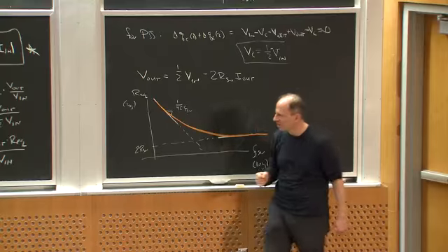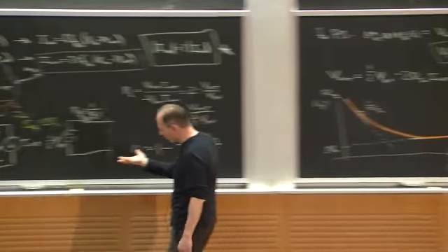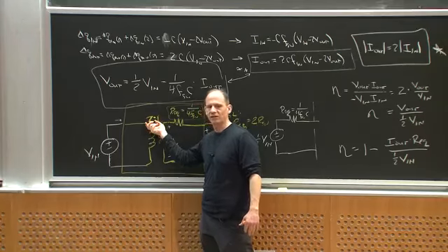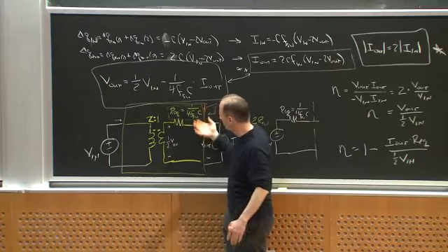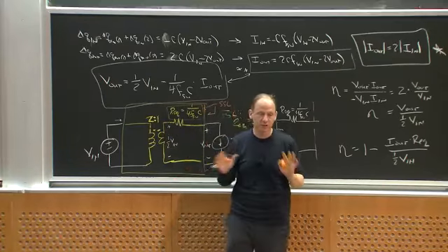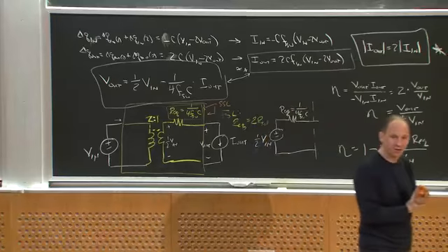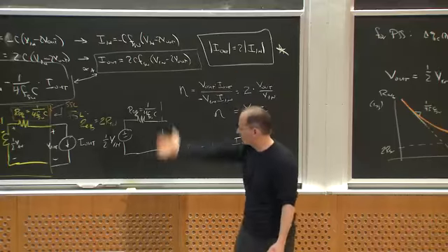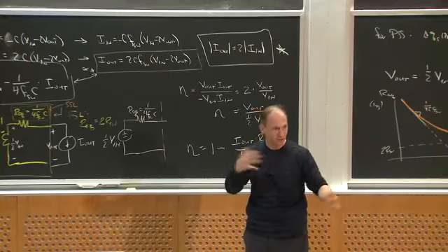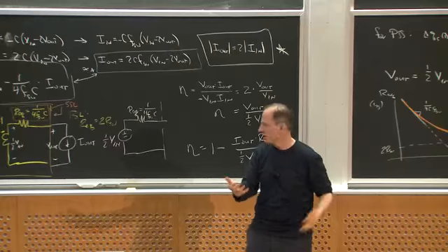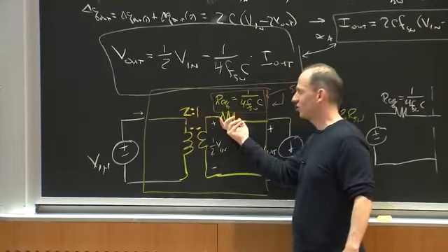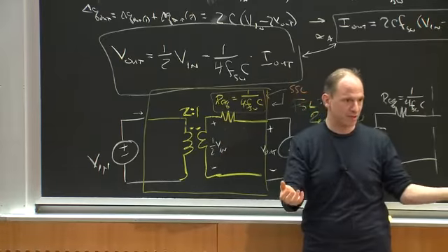And the result of this is if what I want is a fixed conversion ratio close to this, I can get extraordinarily high efficiencies and power densities. If I deviate the voltage conversion ratio away from that, then the efficiencies start to droop. But for what they're good at, switch capacitor converters are very hard to beat. And if I was to analyze any other switch capacitor converter, it's the same deal. It's some charge transfer analysis through the different capacitors, and I use charge balance, and you can work that out to being a current conversion ratio, and then some equivalent resistance with a slow switching limit and a fast switching limit.